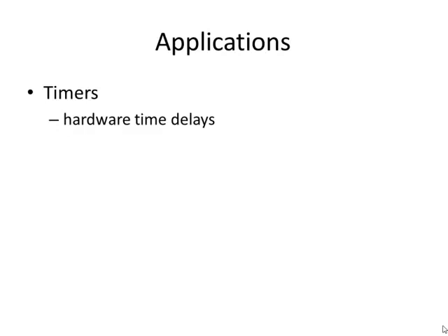So a lot of times if you want to slow something down, let's say you want to make an LED blink, if you just write a 1 and a 0 to that LED, it's going to blink so fast that there's no way a human being is going to catch that. So we quite often use time delays to slow things down so that the microcontroller really just sits there and kills time waiting for the slow human being to catch up.